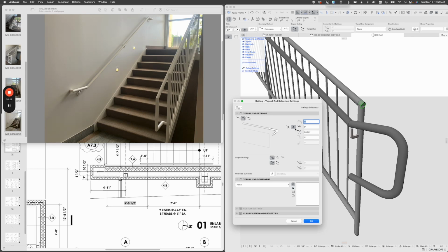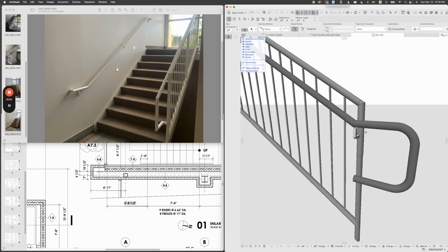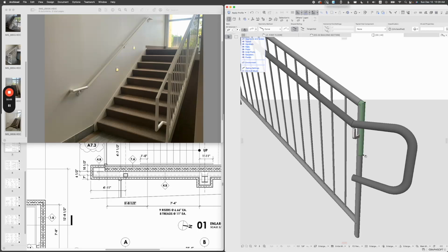It looks like there are settings to turn it left or right, or I could just pick the first one, curving in segment plane, and now I can even fix the angle so it's 90 degrees. And all I need now is to change the size of the extension. So I'll just put 1 foot for right now, just to show it to you. I'll say OK, and as you can see, it started to break down, and that's what I need.